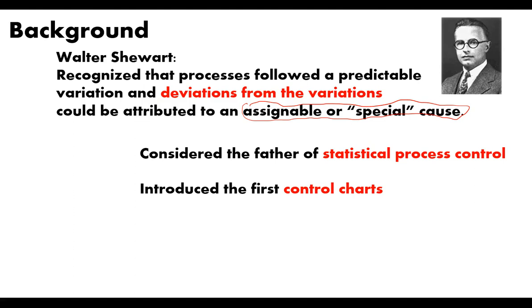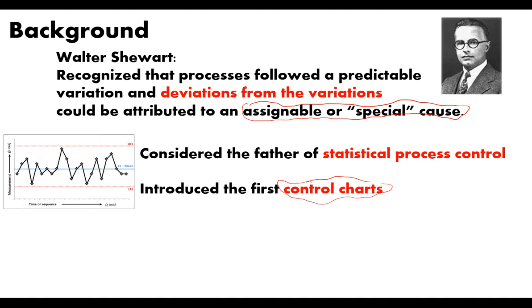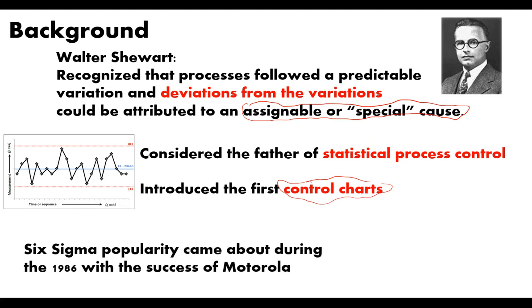So in statistical process control, keeping this first point in mind, you can consider that process and say, okay, how much should I expect it to vary? That's the whole idea of statistical process control. And if you want to map this process over time, that comes into the idea of the control chart. So again, very simple concepts, but very profound effects from those concepts. So that's just a normal run chart, giving some example for those.